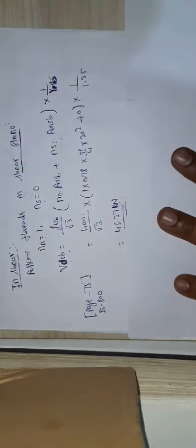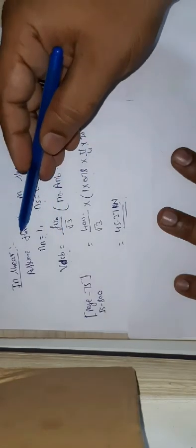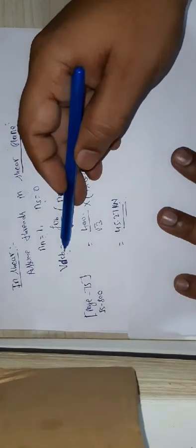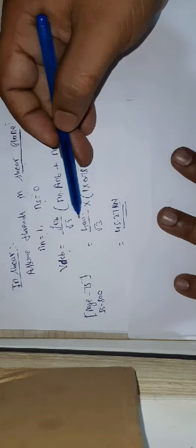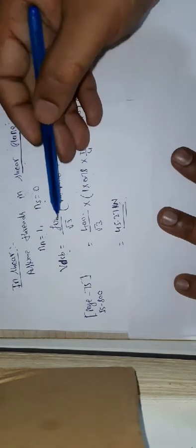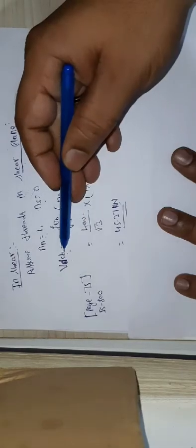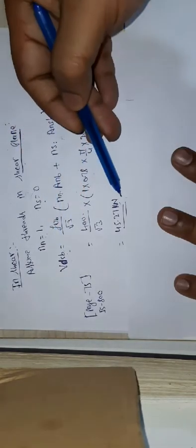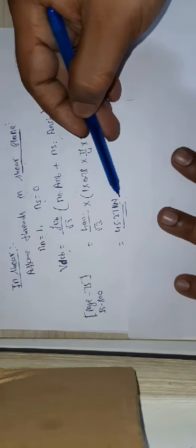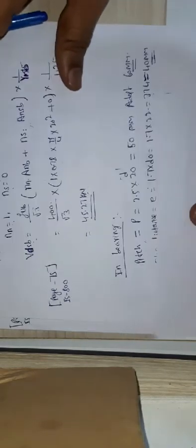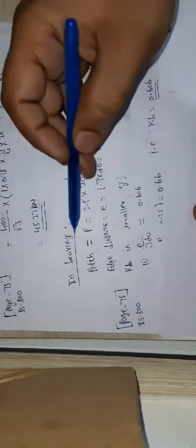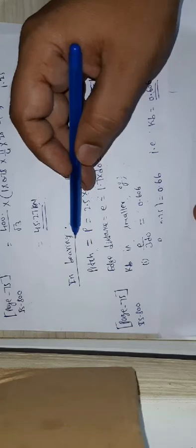Now first, please remember, in connections your first step is to calculate the shear strength of the bolts. Here fub is 400 because its grade is 4.6, so the ultimate strength of the bolt is 400. By using this, I can calculate Vdsb. I calculated Vdsb as 45.27 kilonewtons. Next, now we need to calculate the strength of the bolt in bearing.